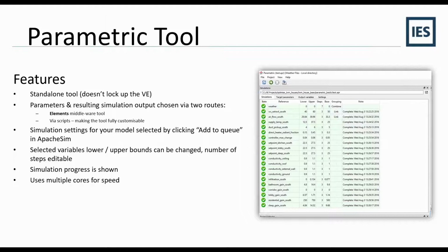The key aspects really here are it's an independent tool to run parametric studies on the virtual environment models, but it doesn't lock up the VE, so you're constantly able to work away. You're able to, through a tool called Elements, create templates to run these parametric simulations. Now what that means is, for the more advanced users, you would be able to create your own templates. For those that are new to this, you may wish to use previously made templates. And again, within a larger business where you're creating a library, you can start to create libraries of templates, so standard approaches to your simulation that you would then use time and time again on other projects. So again, reducing the amount of time that you're spending.